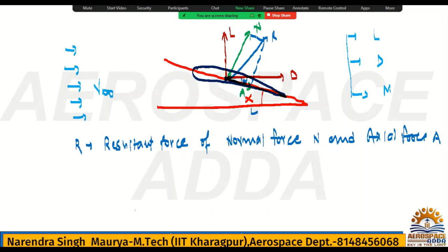Okay, so for the lift, drag and moment, there are various parameters, because here if you check, lift, drag and moment will be depending on alpha, yes or no? If alpha you will be changing, the magnitude of lift, drag and moment will be changing. Okay, because that component will come into picture, yes or no? So here lift, drag and moment depend not only on alpha, the angle of attack, but also on velocity and altitude. Why I am saying altitude? Because density terms will come into picture.